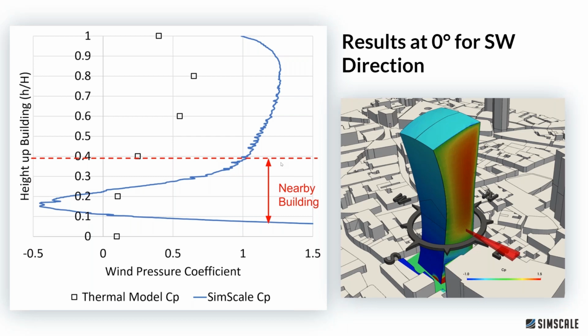But what we're doing is not treating a really critical component, right? We're not coupling the external to the internal environment when it comes to wind and air movement, and this is critical. So we do with solar and thermal. So U values, will spend a lot of time on that. Glazing, will spend a lot of time on that. The treatment of solar gains, people will spend a lot of time trying to do that. But when it comes to wind, for some reason, there's a big gap. It's not treated very well, very academically at all. And what we do is, for some reason, we're just happy to accept these kind of standard wind pressure coefficients that we've had for ages. No one really questions them. But here's a really great example of why that can't continue to happen.